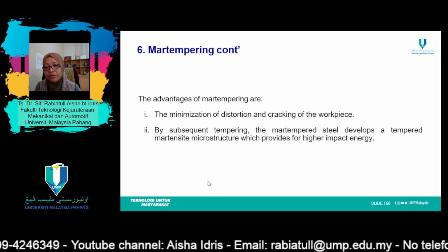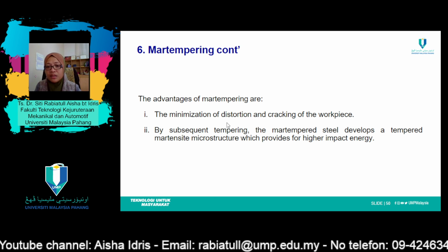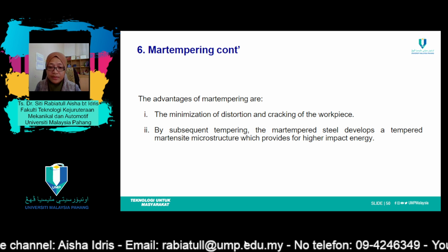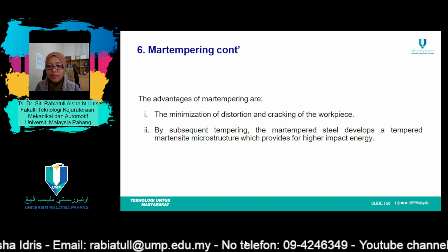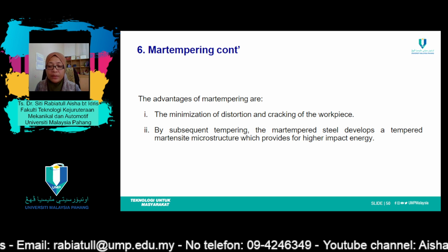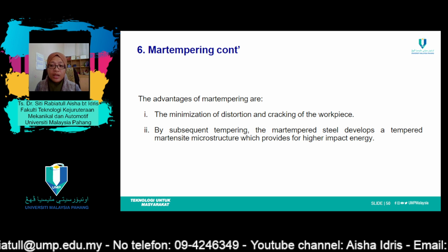The benefits of martempering are to minimize the distortion and cracking of the workpiece. Number 2, by subsequent tempering, the martempered steel develops a tempered martensite microstructure which provides higher impact energy.